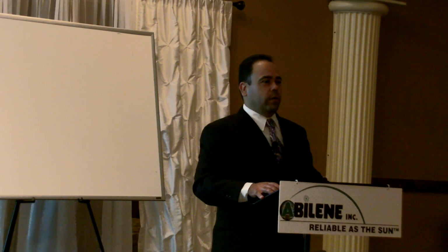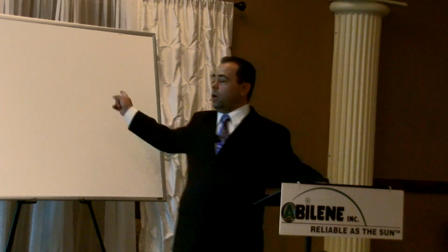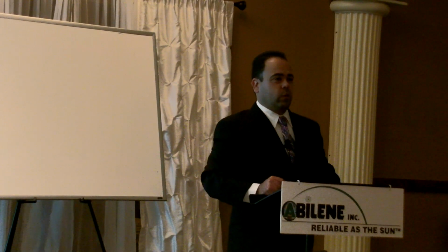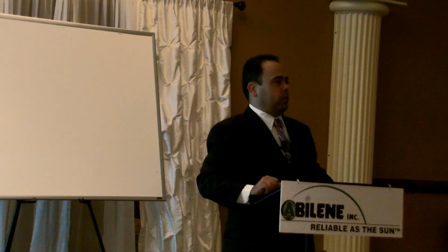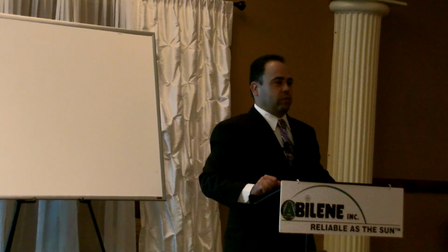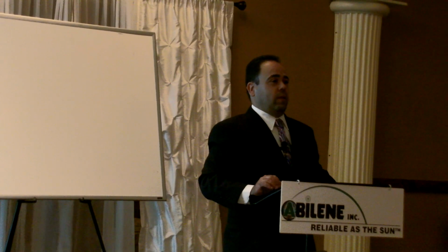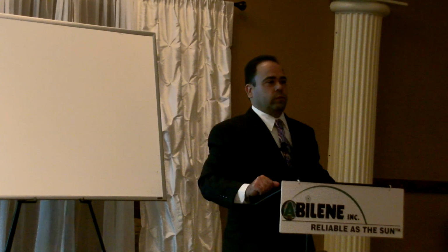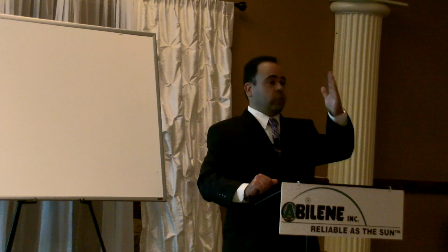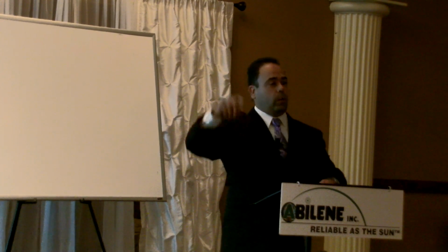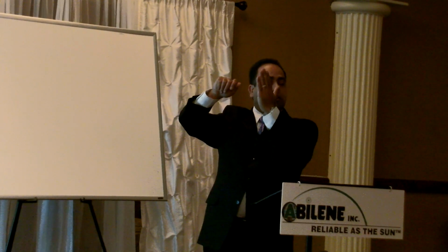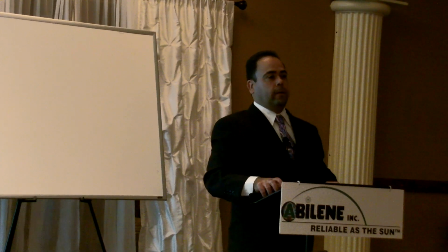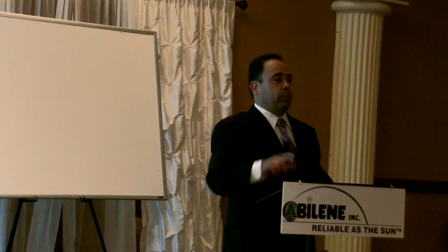So it's very important. As soon as you set this smoke alarm, just like we talked about with the lens, next thing I want you to do is go at the entrance of the boiler room and shut the lights off. And then see if it rings. If it does ring, calibrate it with the lights off. Okay? Put the lens in, have somebody stand at the door, you go up there, you set it, let them turn the lights off, and then drop the lens. Okay? It's a very good point.